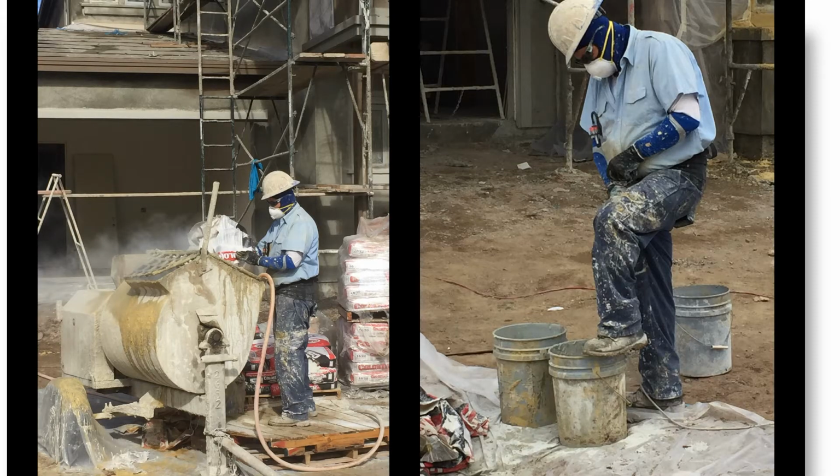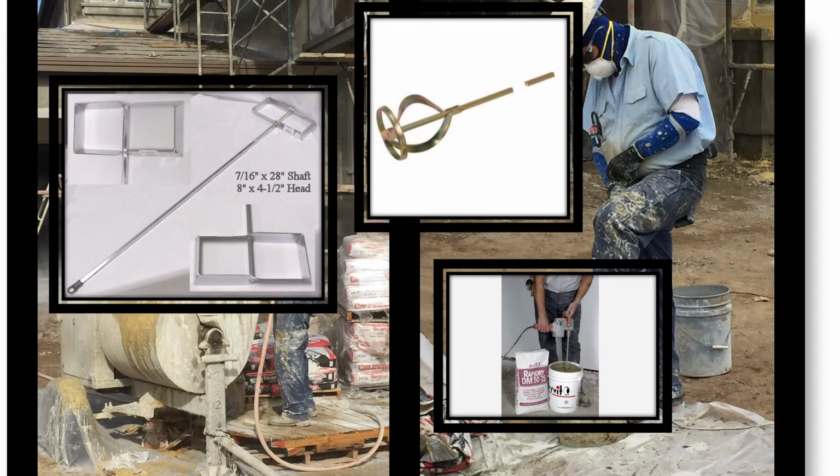Mixing base coats can be done by a variety of methods, including by hand with a hoe and wheelbarrow. Most mixing is done with mortar mixers or using hand drills for smaller projects. It is important to ensure the materials are well blended. The sand particles must be well encased in cement paste, as this is the glue that holds the plaster together. Drills must be powerful enough to blend the materials, and you should use approved mixing bits.